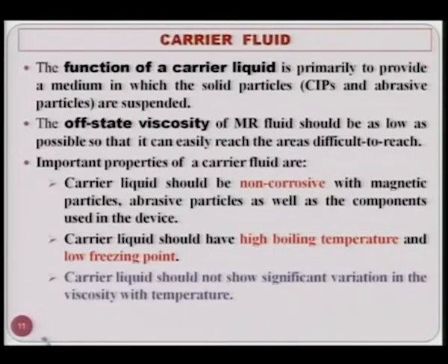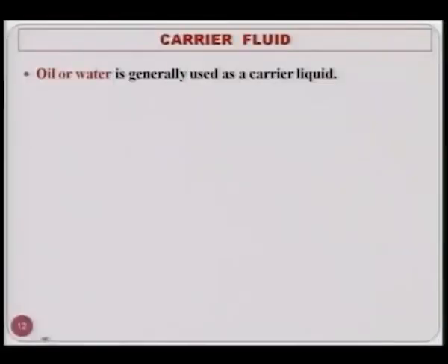Carrier liquid should not show significant variation in the viscosity with temperature. This is another important point, because if viscosity of the carrier liquid or carrier fluid changes, then the characteristic rheological properties of the medium are going to change, which will definitely affect the surface finish that you are going to get finally. Oil or water is generally used as a carrier fluid.